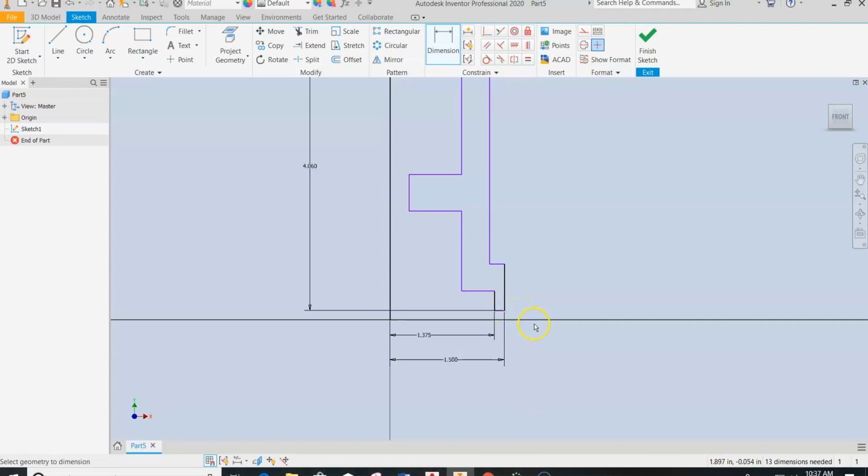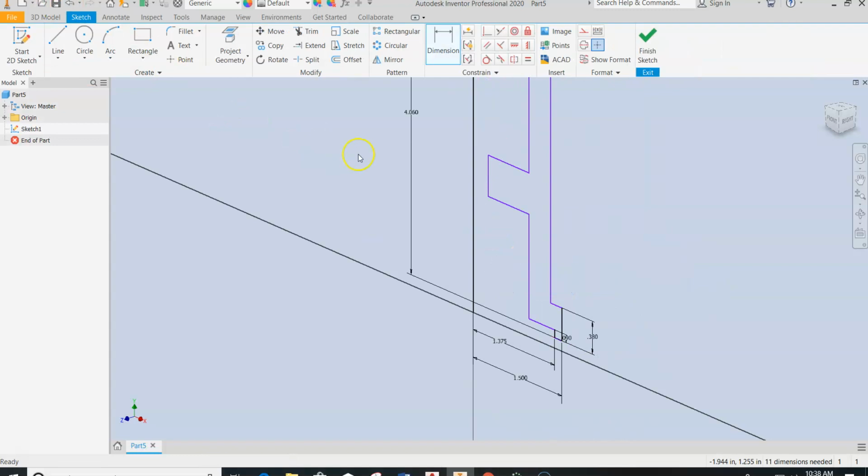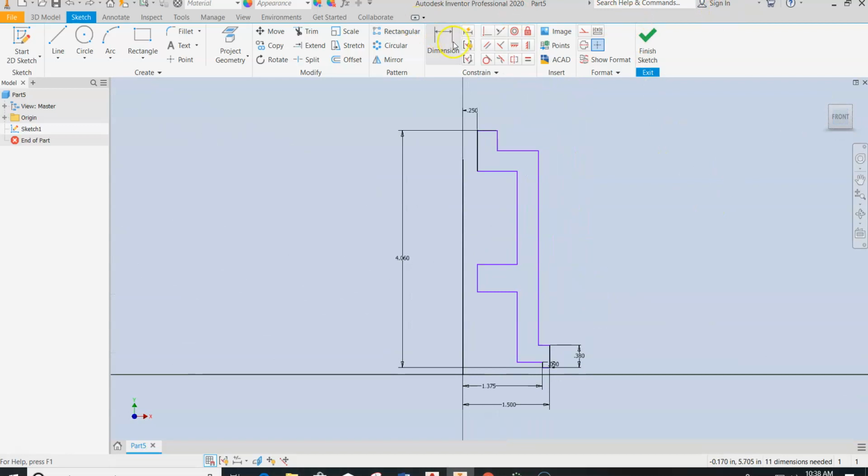The profile for that, it's 0.09 tall. So I'm going to go ahead and place that dimension while I'm here. So that's 0.09. Look into the outside leg of this one. This is 0.38. And while I'm here placing some of those dimensions, I did not mean to do that. I'm going to go ahead and put the 3.25 dimension. So the 3.25 is from this leg to the bottom. Nope. 3.25 is from here to here. 3.25. So that sets that.